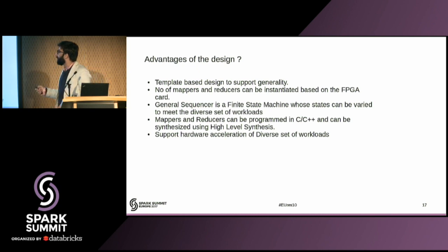The advantage of the design is that it is a template-based design to support generality. You could instantiate the number of mappers and reducers based on the size of the FPGA card. Then this general sequencer, which is a finite state machine, is the tricky part, because its states can be varied to meet a diverse set of workloads. Depending upon how you want to schedule the computations on the mappers, you could do that just by adding or removing states from your finite state machine.